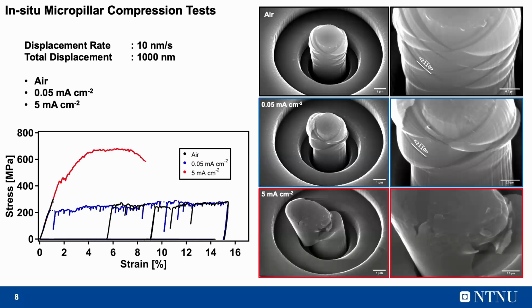However, I'm not sure it's visible from here, but in the solid solution hydrogen cases, you can still see the large slip traces, but there are also small intense slip traces as well, which indicates more continuous and frequent strain bursts happened during the solid solution.